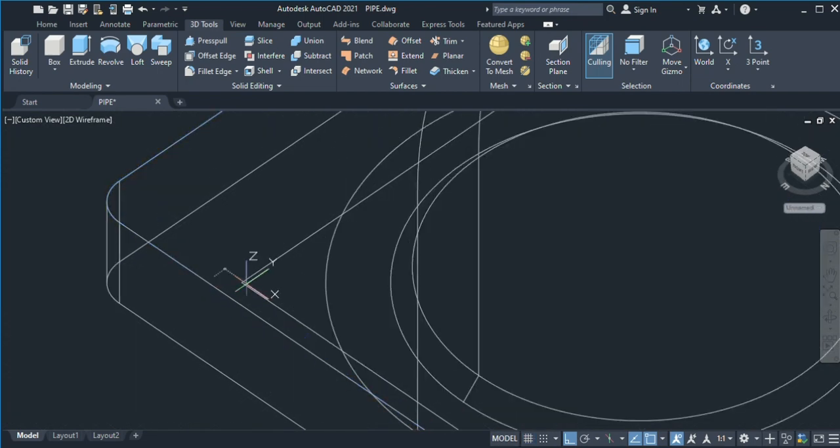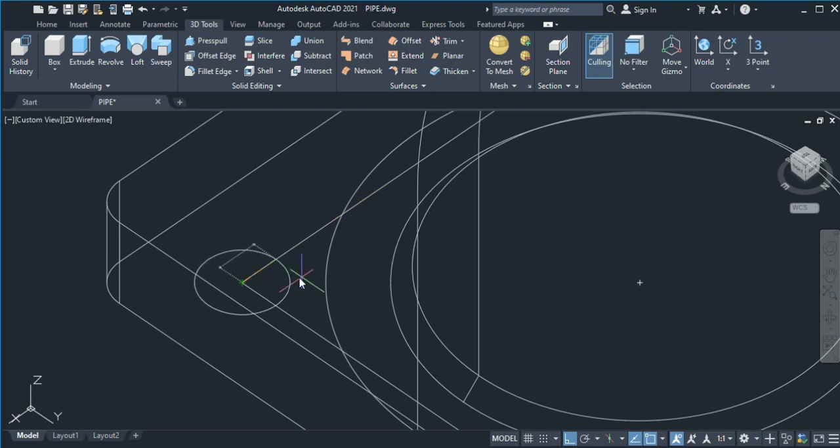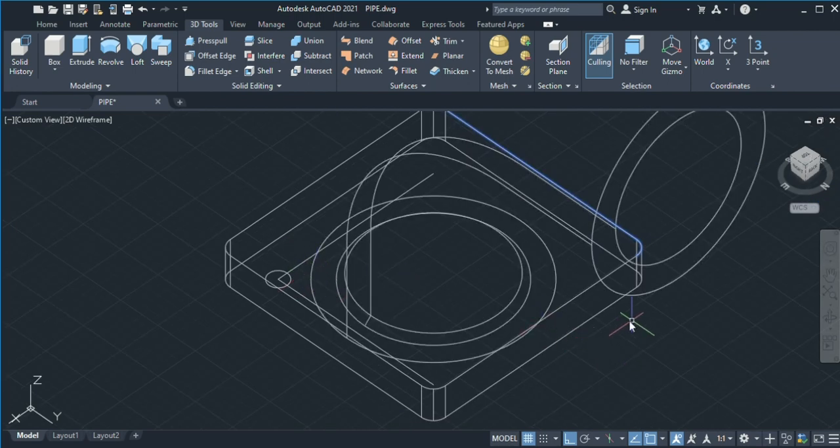We have small circles, which can actually be done with two different sizes of circle. One is diameter 30 and the other one is diameter 60, if I'm not mistaken. We do it there. Then we create the cylinders, 4 of them, one for each edge, with the height of 50, which is the same as the block.